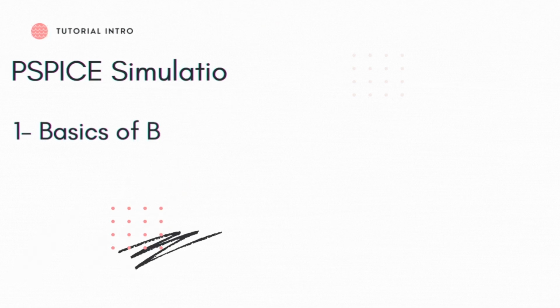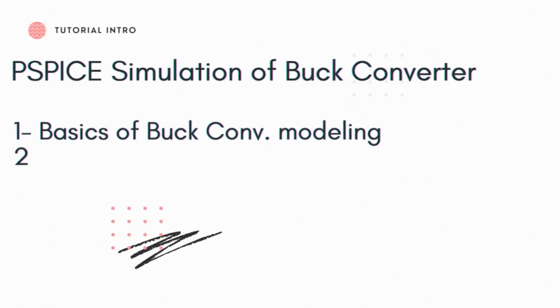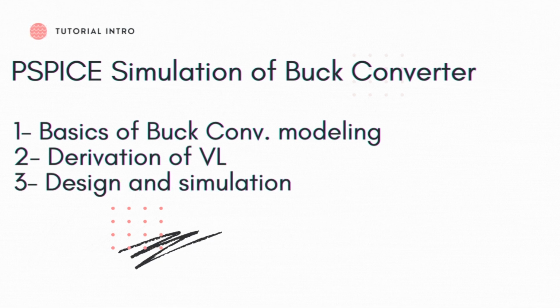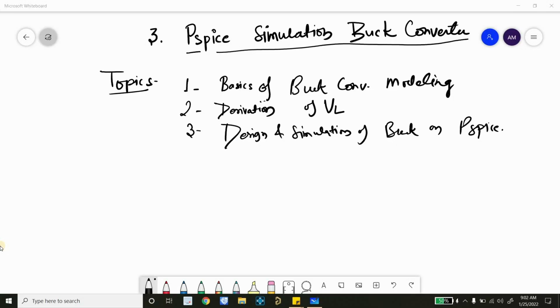Now in this video we're going to discuss buck converter and we will simulate it on PSpice. There are three topics that we're going to cover. The first topic will be basics of buck converter and its modeling. The second topic will be derivation of voltage across inductor, in terms of its D off and D on, plus the amount of current which is flowing through it. Apart from that, we're going to discuss design and simulation of a buck converter on PSpice. So these are the three topics that we're going to cover in this tutorial.